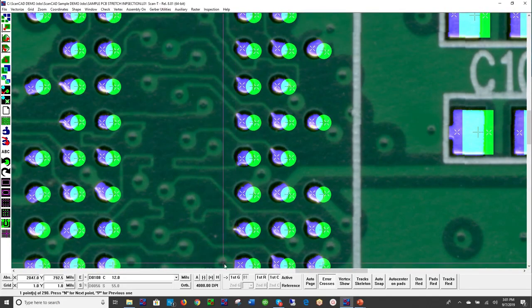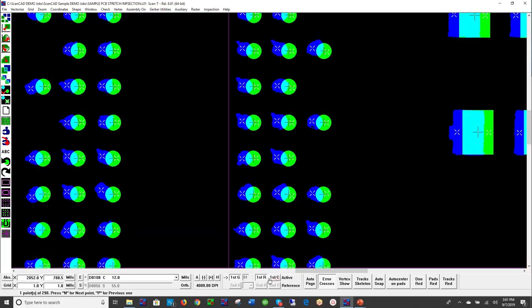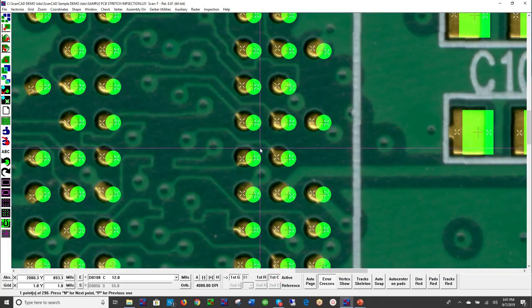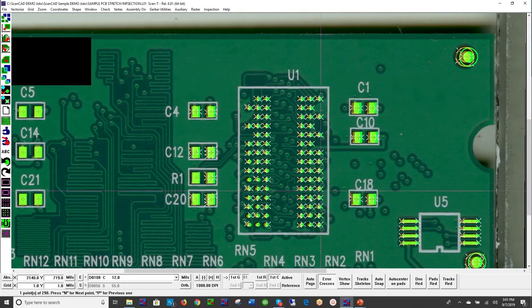Well, what this represents is this Gerber data, this green CAD data, represents a stencil that's going to print solder paste on this board. What Motorola's study suggested is when you have this situation, we have 125,000 of these boards that we just paid for. The boards are within tolerance. The stencil data, if we cut the stencil, would have a problem.